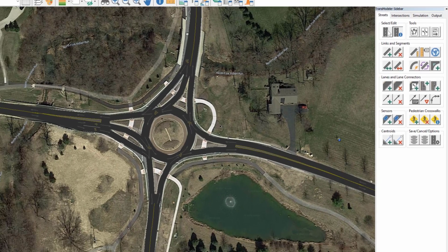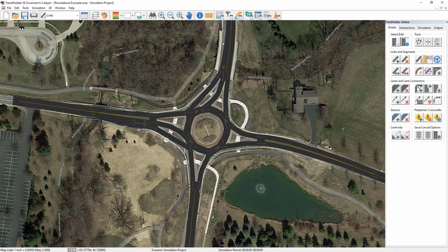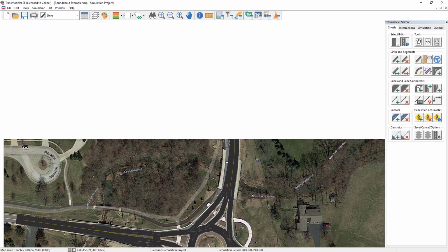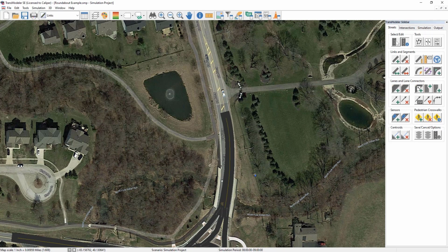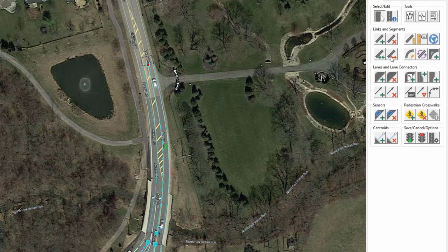Last, add the median at the southbound approach, using a similar order of steps applied for the eastbound and westbound approaches. Choose Select and click on the link at the southbound approach to enter the editing buffer. Choose Split and click on the area just below where the hatched pavement markings end and separate the opposing lanes.